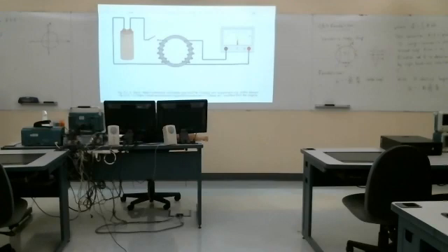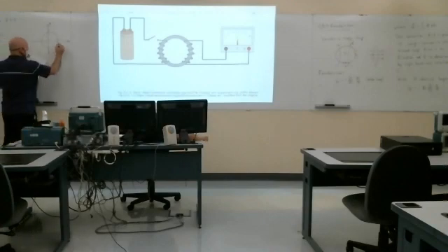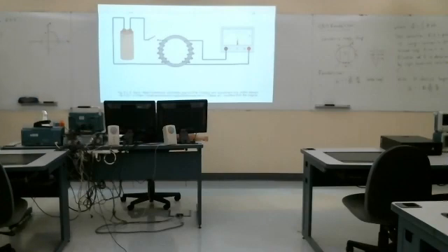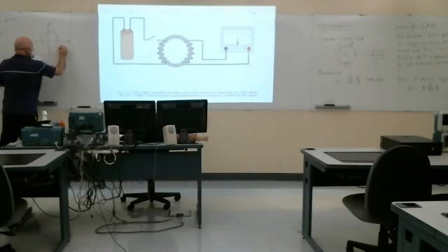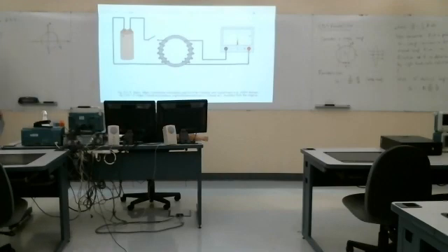Here in the problem, they specifically state that the plus terminal is plus phi directed from the minus terminal. So they give us the polarity in the problem statement, and that doesn't really matter. If you had chosen the opposite polarity, you would just get the negative result, right? A negative voltage just means that the polarity is, it's not wrong.